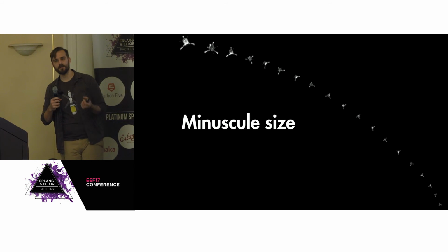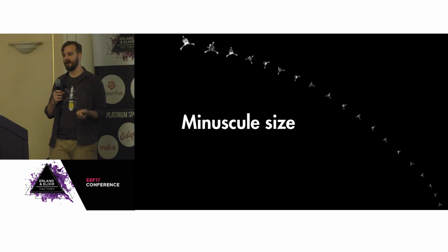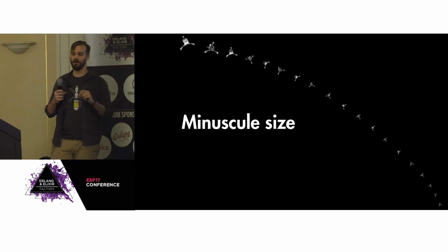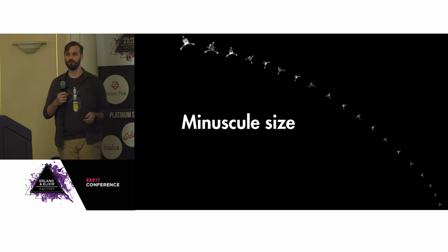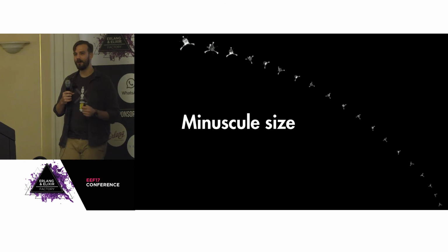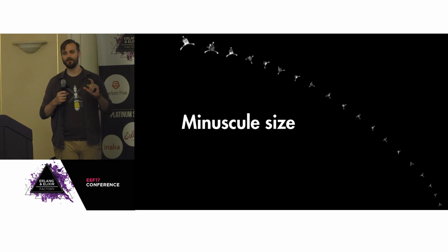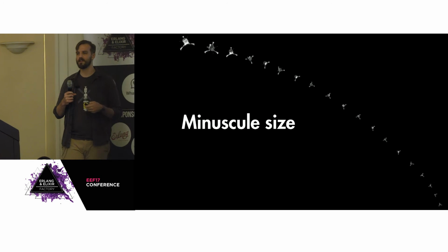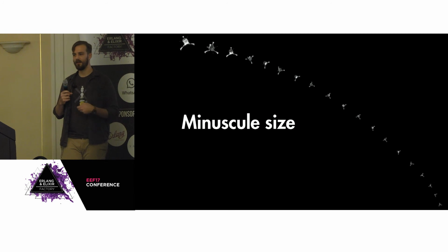But this lander is really interesting because it has such insanely low power capability. It runs an 8 megahertz, 8-bit processor. And the reason they used the particular processor, which is the RTX 2010, was because it had the lowest power profile of anything available in the market. This lander also had to be programmed in Forth, which if you've ever programmed Forth, I highly recommend it. It's a stack-based language, and it's barely a language, but it's designed for density. So it crams itself as much as possible onto the available system. So they were able to put an entire scientific package on a couple watt robot that would soft land on a comet and send information back to Rosetta, which would do the beaming back.